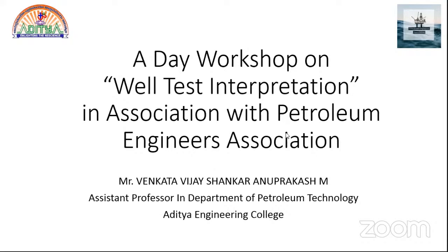And what about the analysis using the surface-based acoustic fluid level? I think in certain cases, if you directly place the recorder against your wellbore, that will be better, instead of doing it from the surface. Some disturbance will be there if you are using the acoustic fluid level survey, because of vibration or anything, or because of the flow also you may have some disturbance.